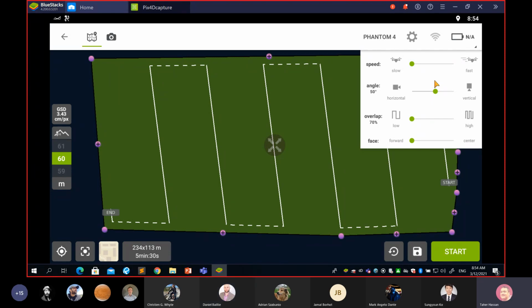If you make an oblique image, in this case, you get better elevation accuracy. In addition, something you're not paying attention to: if you're making a vertical photo, probably you will only capture the top of the building. But if you make an oblique photo, you will also capture the sides of the building. Okay? Anyway, next is overlap. The overlap is simply the overlap. We will talk about overlap in lots of detail in the next class.